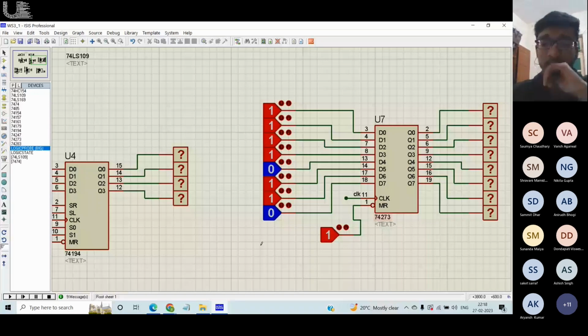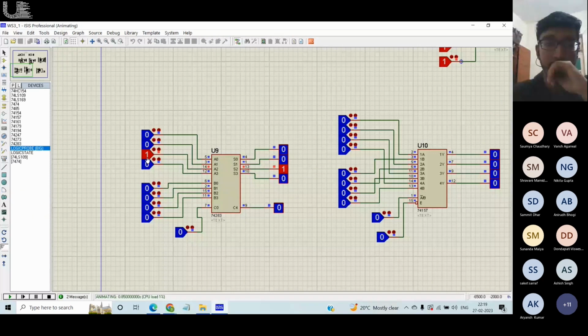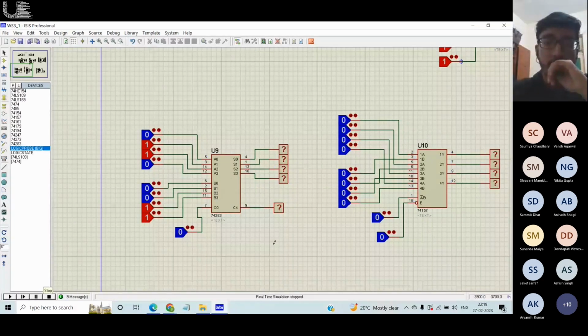Now coming to something from the last workshop, it's a simple adder, right? A very simple adder that we're having here. So see, 6 plus 4 is 10. 10 becomes this, and if we're giving this, we have a carry output of 1 here. So it's a 5-bit number. Two 4-bit inputs, and we're getting a 5-bit output, right? As simple as that.